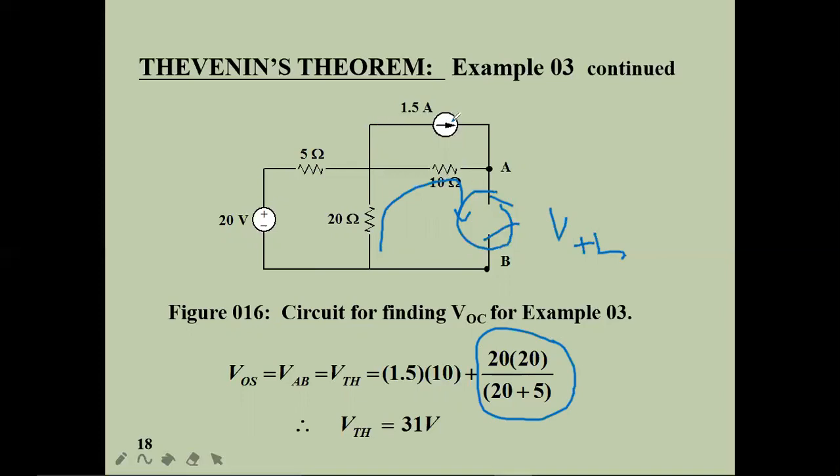How are you going to find the voltage drop across the 10 ohm resistor? Here I have given the current path. The 1.5 amps of current is flowing in this direction. Since this is an open circuit, the current obviously chooses the 10 ohm resistor. The current will not flow through A and B, so the total 1.5 amps flows through the 10 ohm resistor.